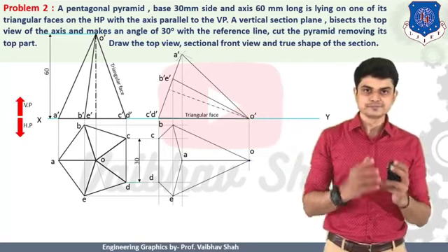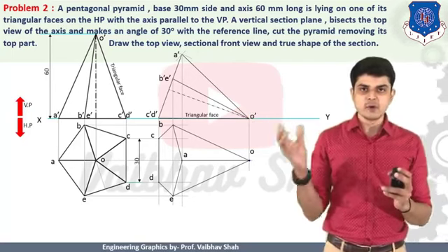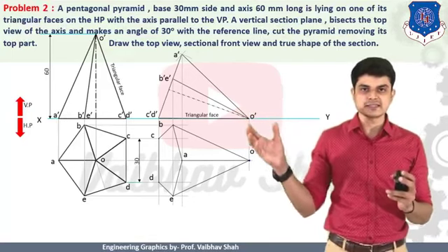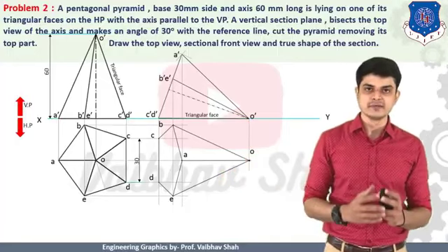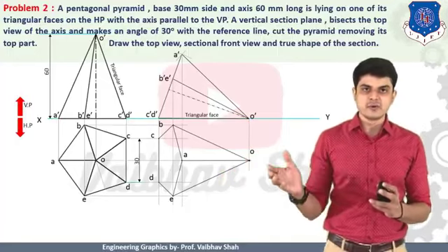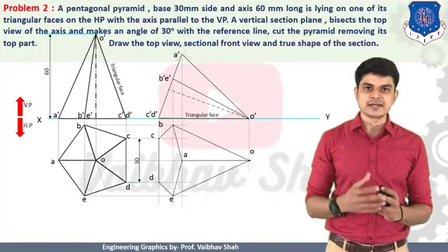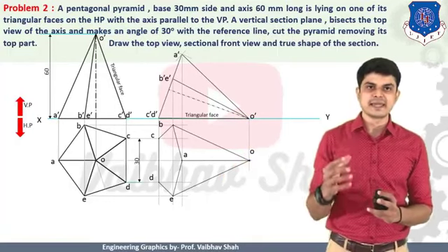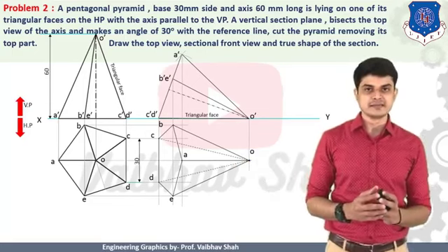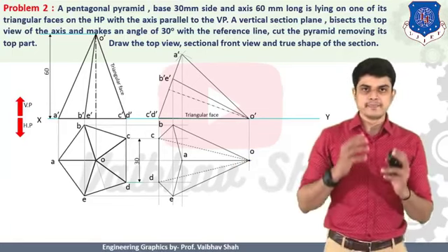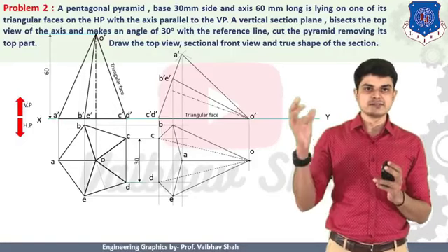So that means the lines connecting your O dash C dash and O dash D dash in the next view, that means the top view, must be hidden lines or dotted lines. So let us put these lines OC and OD as dotted lines because they cannot be seen by taking the top view from this top direction. So we have drawn these two lines as hidden lines. Right? Very easy. Now we have drawn our object in the said position.